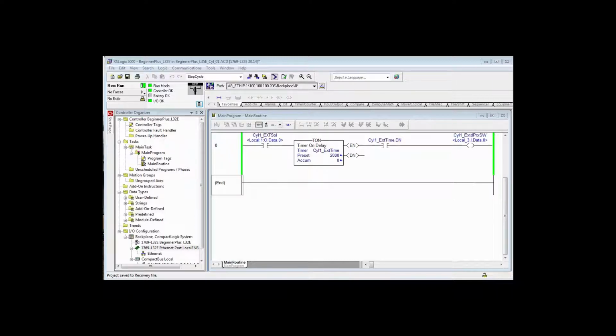Those of you that are more used to the older format for programming that was more true to electrical, you have to get adjusted to this style where we put loads in series. A TON instruction is normally considered an output type instruction, and that's simply because a time delay relay had a coil, but it had control lines that controlled how it behaved.